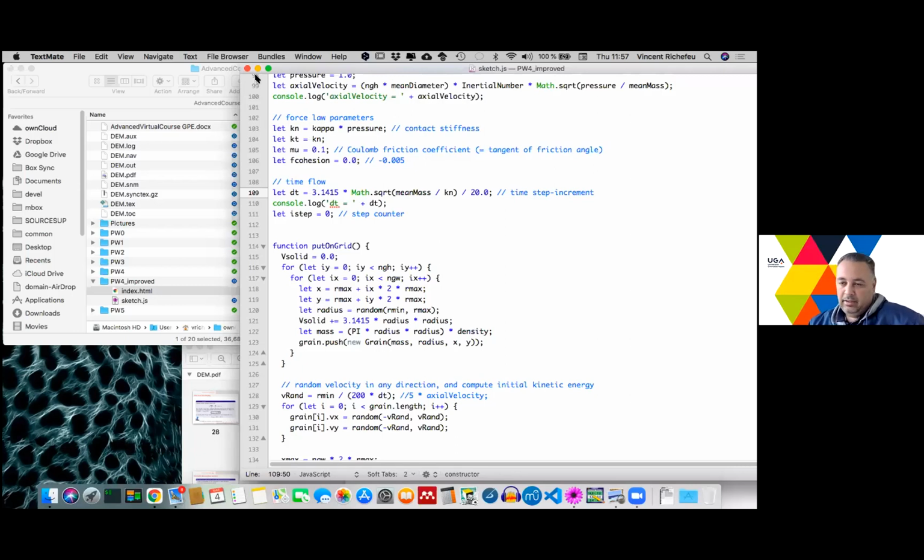finally the stress. Okay, so the idea is to be able to apply a velocity on the boundary instead of a force. Yes. So you apply a velocity, but you get a force on average, which is stiffness. You update this velocity as a function of the force that you measure. Yeah. The force of the other particles that act on the wall.